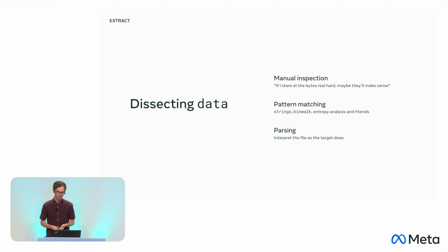And that's, for example, what standard ELF tooling is, objdump, readelf. These things are parsers for ELF files. And they're readily available because ELF is a very widely known and used format. Unfortunately, most firmware formats that you find are going to be completely custom. And you might get lucky and find a tool someone's written to parse them. But in many cases, you'll have to write your own.